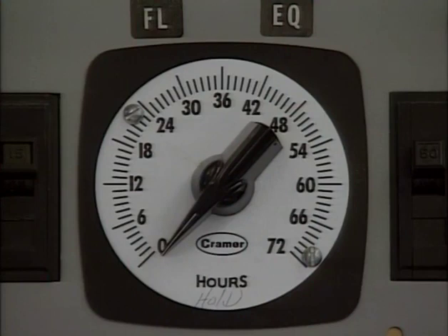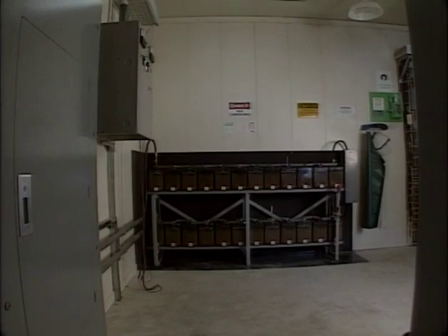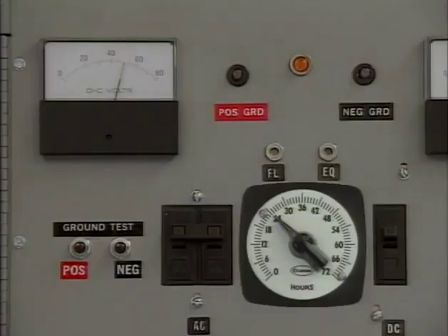After the battery has been properly given a freshening charge, it's typically placed on float charge. Freshening charge voltage and times can vary with the type of battery used and with the load limitations of the DC system. Be sure to determine the specific freshening charge voltage and time requirements for your system. This part of the program covered the definition of a freshening charge, when it's applied, and the basic steps for applying it.